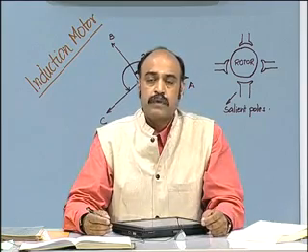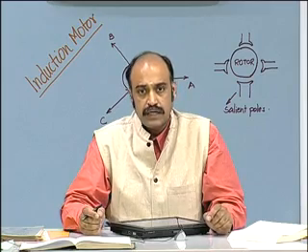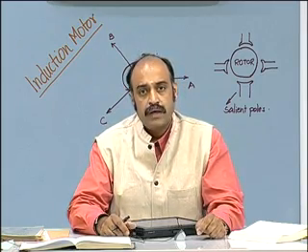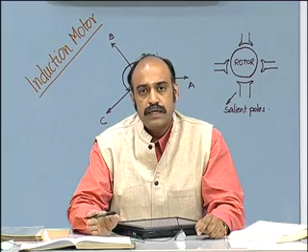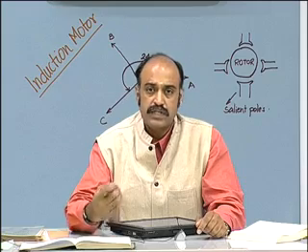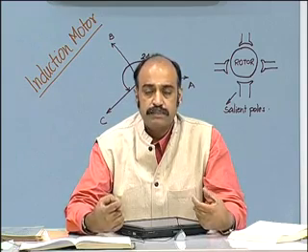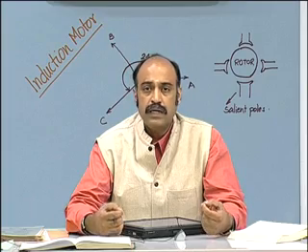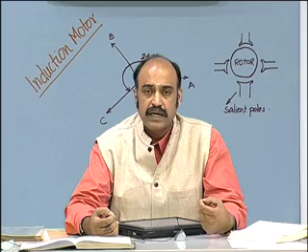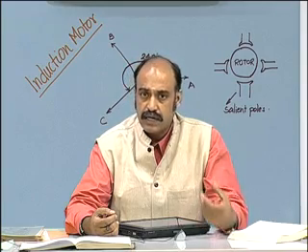Now, when the rotating magnetic field is moving in the air gap and cutting the rotor conductors, initially the rotor is at standstill. That is, it is not moving. So the relative speed between the rotor and the rotating magnetic field will be determined by the frequency of the stator itself.